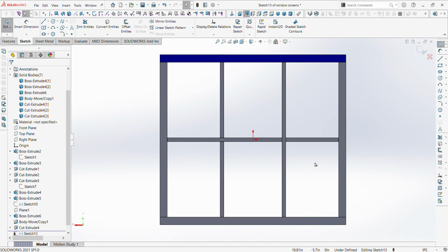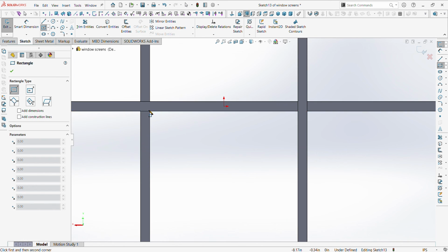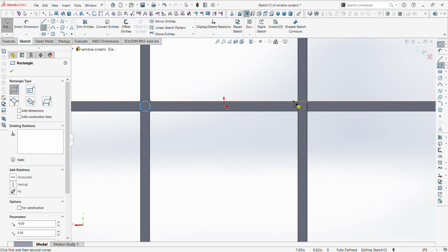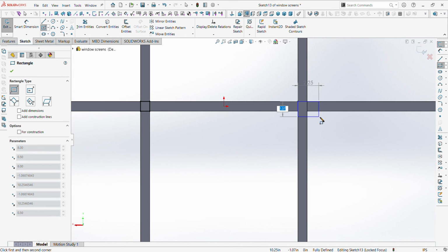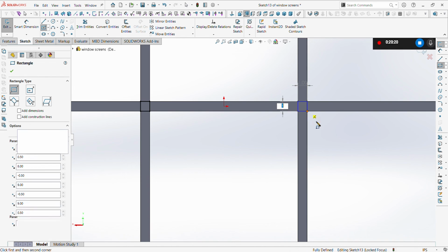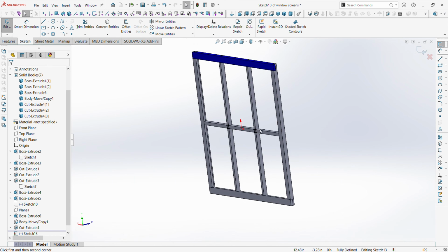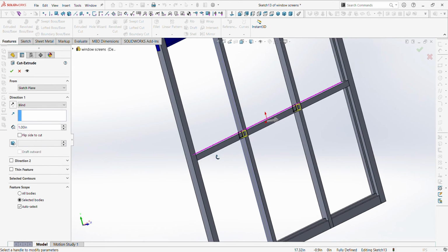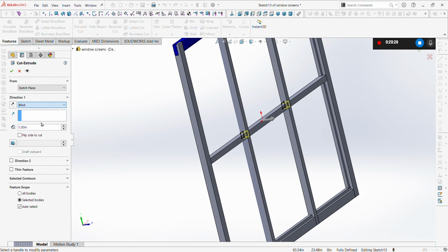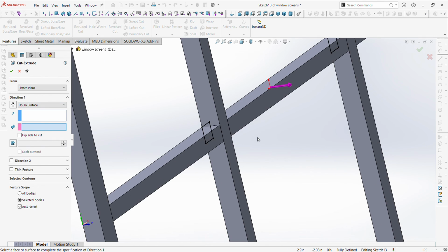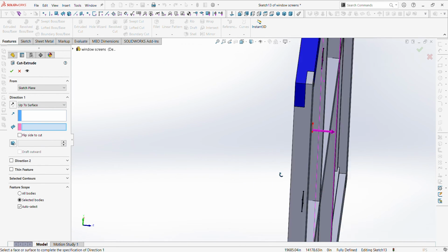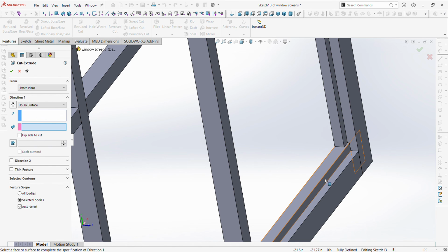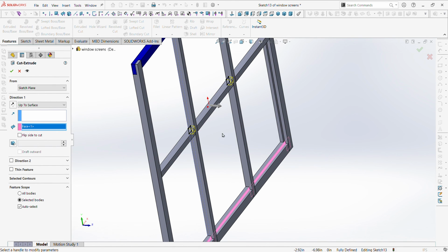Sketch plane selected. Here, we're going to go like that. Give me the intersection, line, intersection. Alright, all black. Another extrude cut. Alright, blind, nope. Up to surface. We want the bottom of the notch. That's the one.